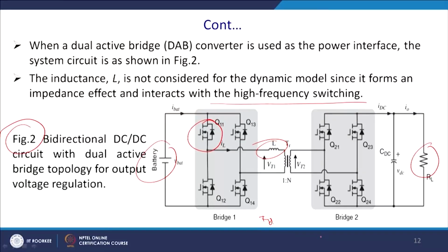So, whatever solar is taken, if it is DC, then there is no problem, you can instantaneously feed this value. But if it is AC, with solar and battery feeding a microgrid, there will be an instantaneous variation of double frequency, and maybe that current is fed from this battery instead of the load, and thus bidirectional flow is possible.